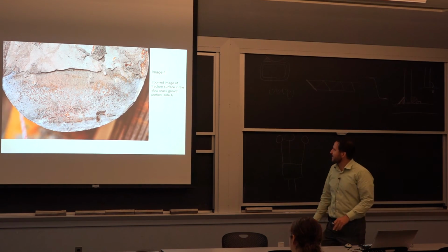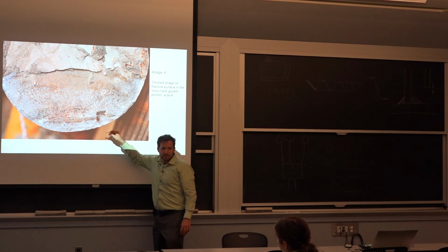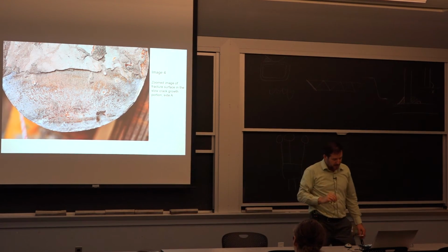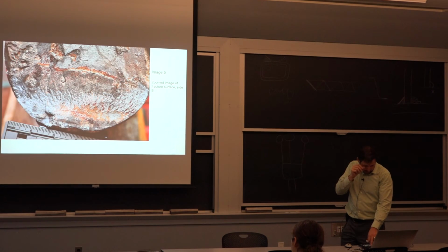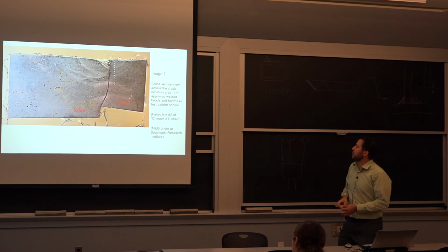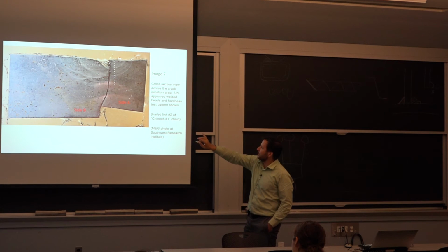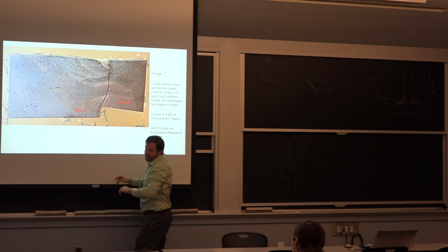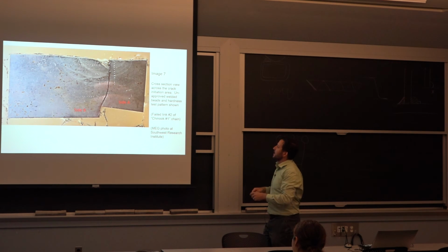If you look closely, there's something with the material here that definitely looks different than beyond that. So the first about 6 millimeters of propagation through this chain is different. So we went on, did some analysis. There were some secondary cracks. Here's what I wanted to show you. So going through the cracks, you see these. This is a polished section, and the crack is here. And we did put the pieces back together in this case. After looking at them carefully, it was just one side of the fracture.